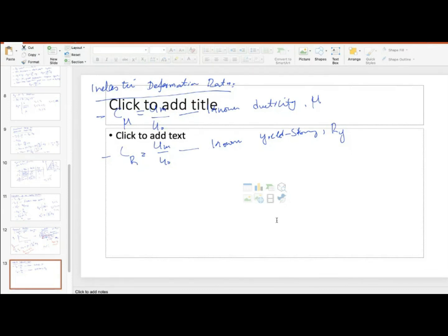Well, it's a very simple exercise. I think we can do it. The first thing that you have to do is to do the modal analysis, and then for every mode you have to read the displacement values. So it's like in SAP when you do the modal analysis. For every mode, it gives you a deflected shape, and for that deflected shape, you have to read the displacement values. Then you can normalize them.